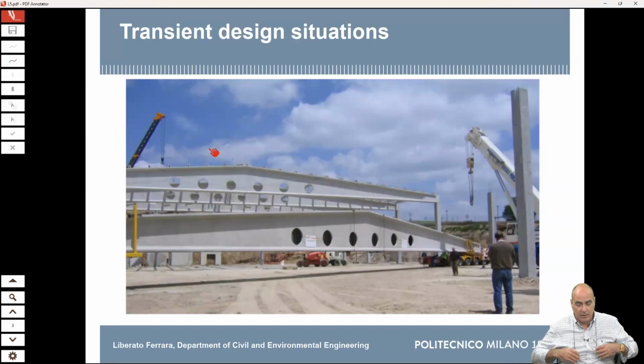Because when you are installing the building, you can also see here that there are some elements which connect, and then you will use them to support also the roofs. These elements, you can also see their shadow on the other beams. Well, those elements then act like struts between the beams that prevent any movement in the out-of-plane direction.